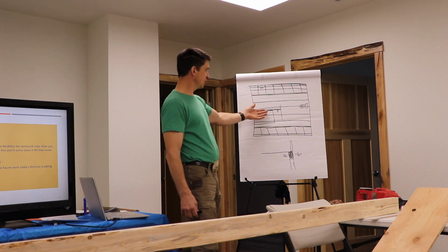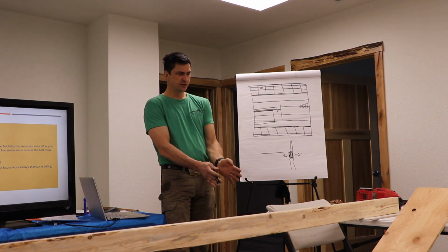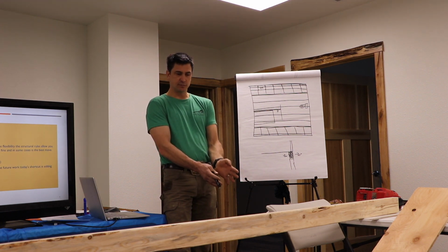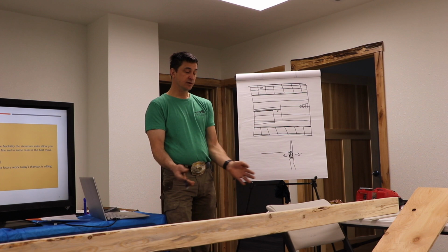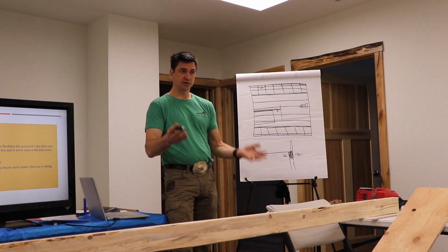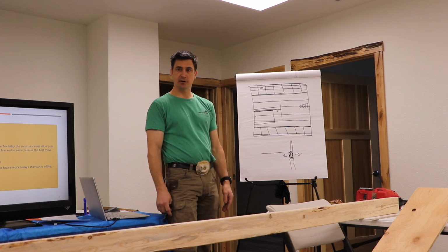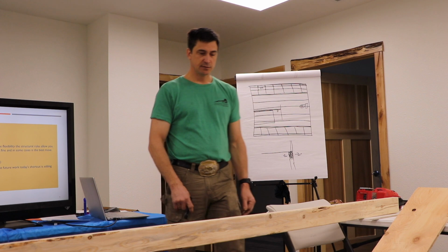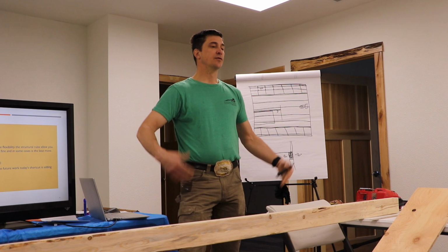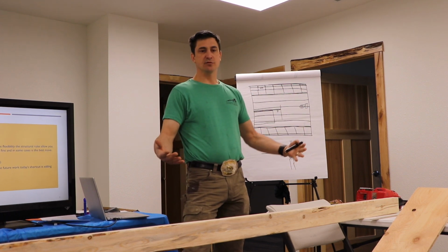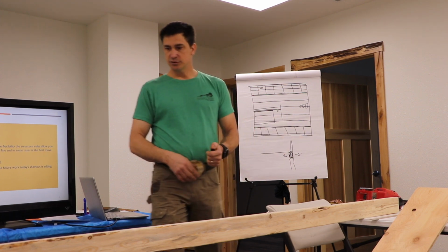And when you run into this stairway opening, you're like, whoa, we've got a floor joist 3 inches away on layout from this. What if we pull our layout from the other end? How does that come out to our stairway? Because I can't move the stairway, but I could change my layout, pull it from the other end. Oh, look at that, it comes right on layout when I come from the other end. Okay, let's just start our board over there, and we'll run it this way. Those are the things why God gave you a mind that can think, that you can pull alternate solutions in.